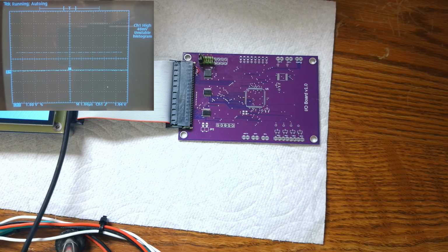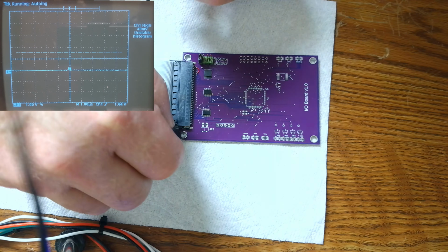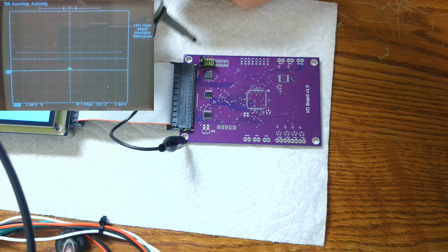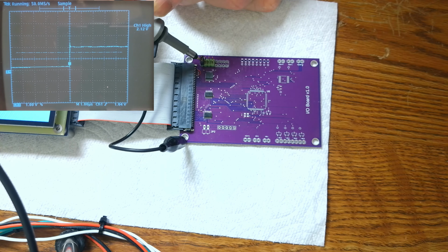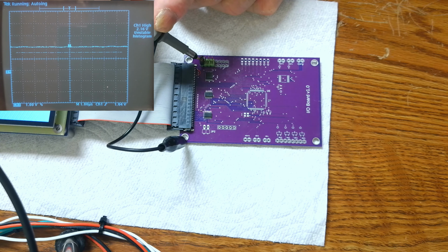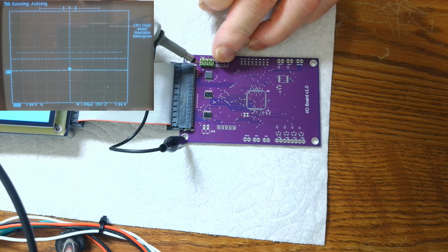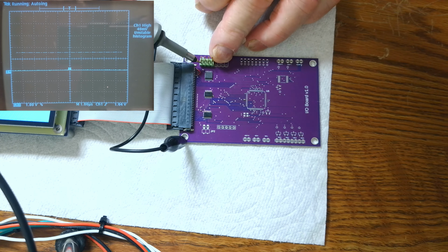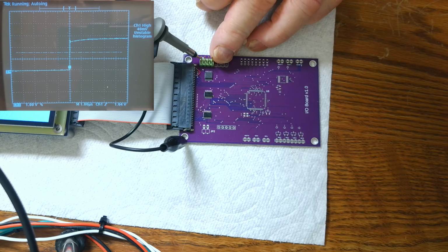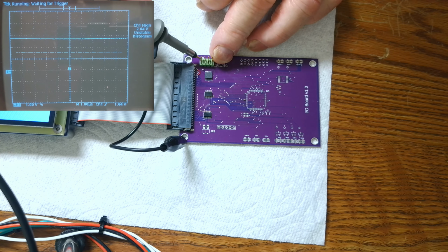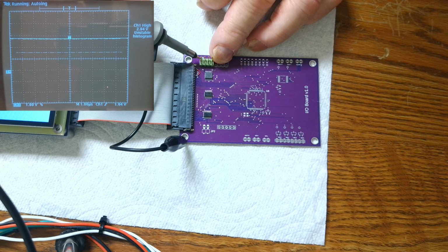So it looks like our address, even though it's selected low, it's being pulled up a little bit. Let's pull that off of here. So we got this guy's on low, and this guy over here is being pulled high. So they're fighting each other again. What is going on with this chip?